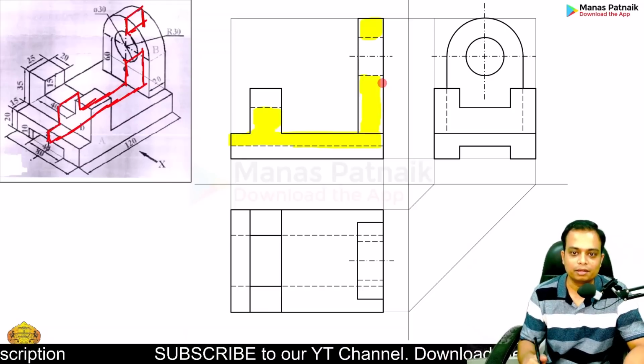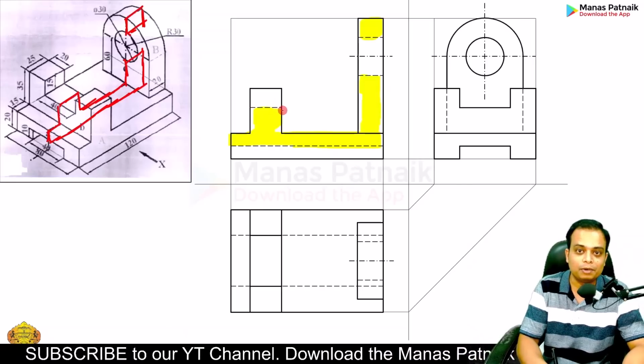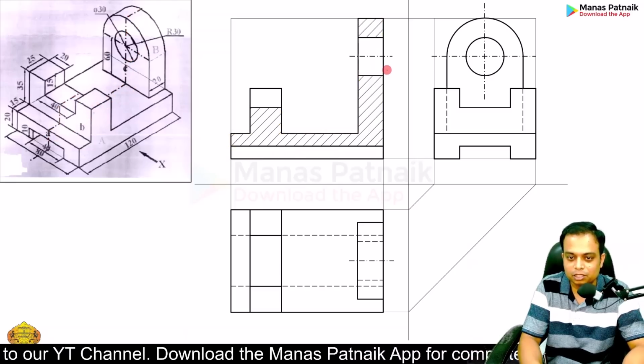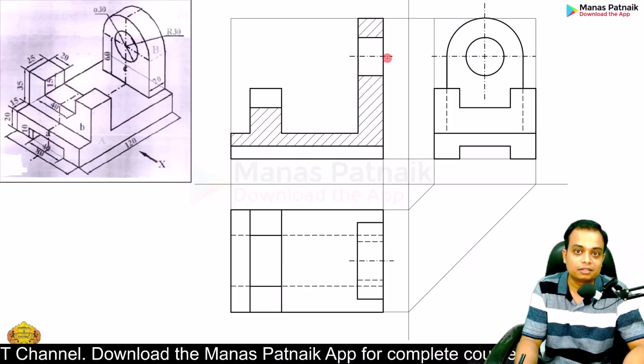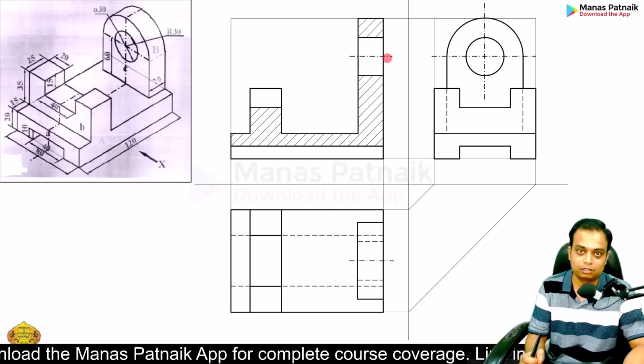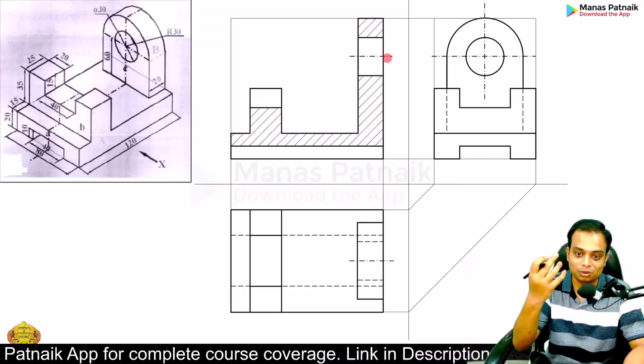Wonderful. Okay, please observe how these hidden lines have been replaced with solid lines. Beautiful. Hidden lines replaced by solid lines, and that's the beauty of sectioning. You get to see the internal hidden details of an object, right? This was the transition that I wanted to showcase.